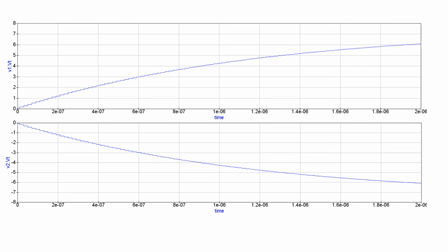The results of the transient analysis are shown in this slide. I chose some arbitrary values for characteristic impedances, line lengths, and resistance values, and these can be changed easily. Physically, once the switch is closed, voltage waves are launched down the transmission lines. Due to the connection of the load to the transmission line, some small but finite voltage appears across the load almost immediately. At each end of the transmission line, reflections occur and voltage waves bounce back and forth.